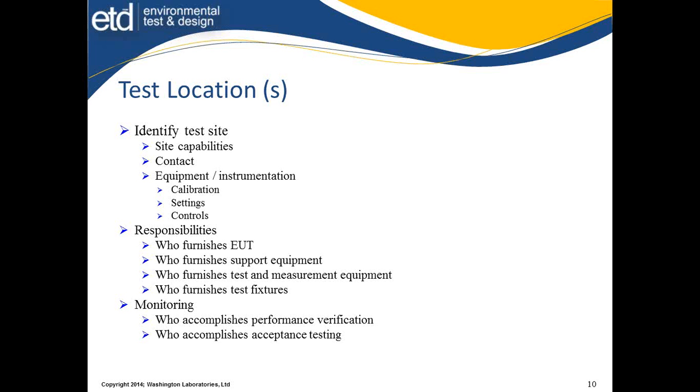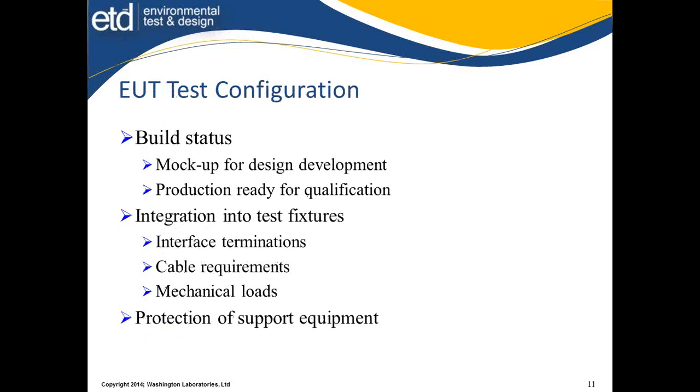So those things can be fairly significant in the overall scheme of things. You need to define those things. The test configuration, the build status. Is it a mock-up for something to develop in the design, or is it production ready for qualification? Production ready does not necessarily mean built by a production facility, but it should be built with production processes.